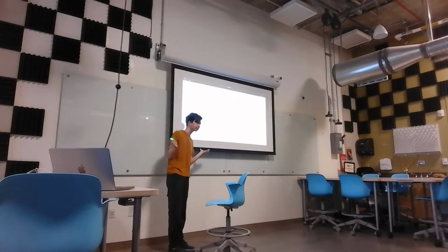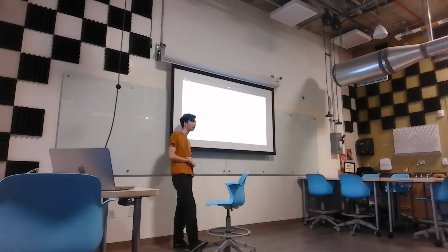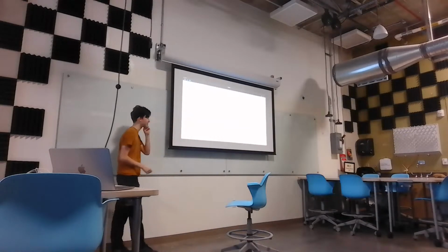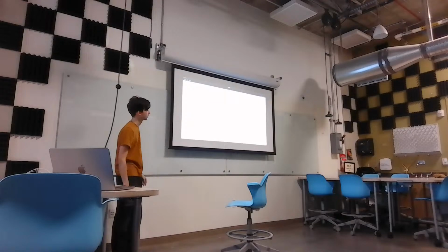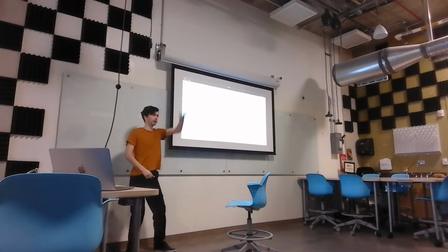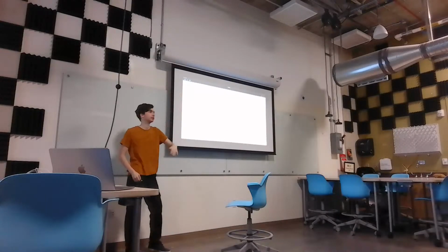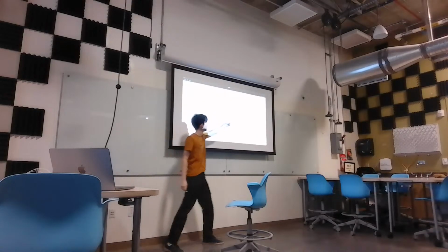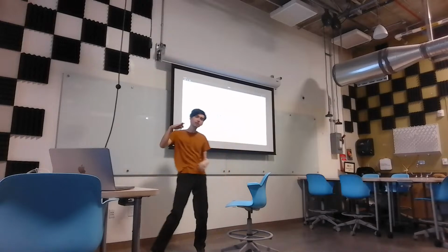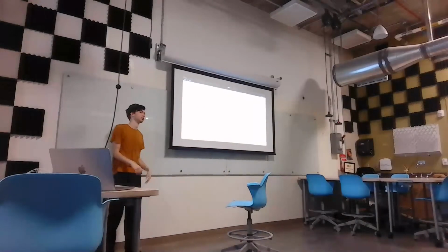For the first time ever, I used LTspice to simulate something outside of class. Isn't that crazy? I needed it. Good thing I said DC65. This is a basic little circuit where I have this simulating our half bridge, outputting high, low, high, low, high, low. It feeds an inductor, a capacitor, and then our LED with a little 1 ohm resistor, just to smoothen that slope out a little bit.